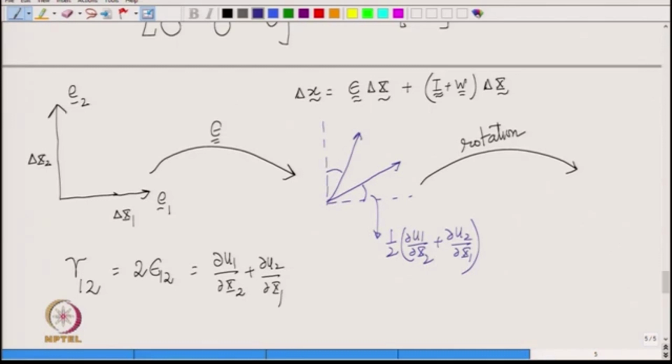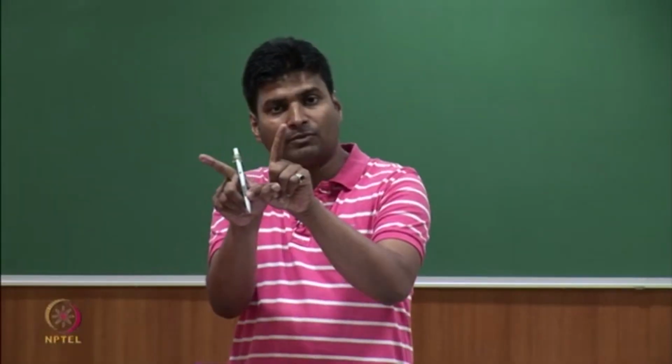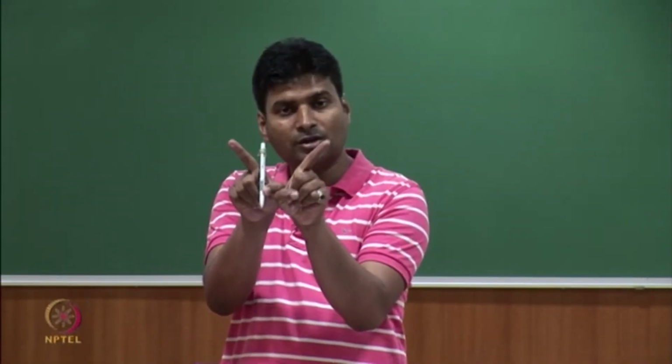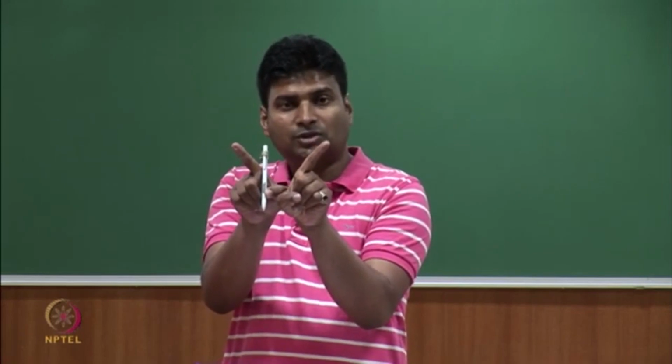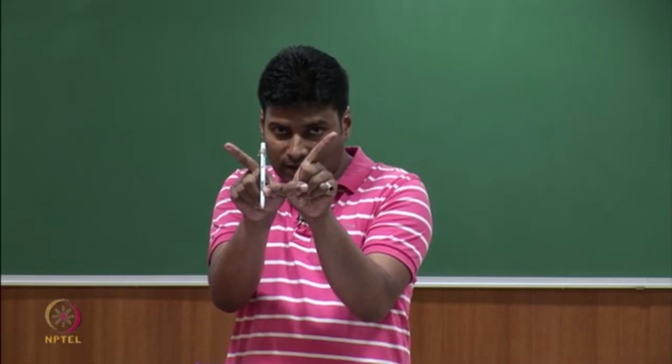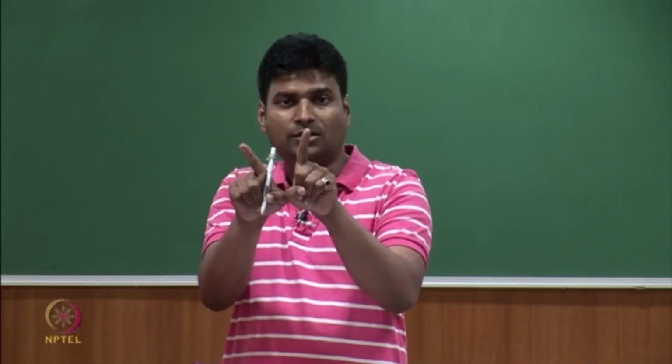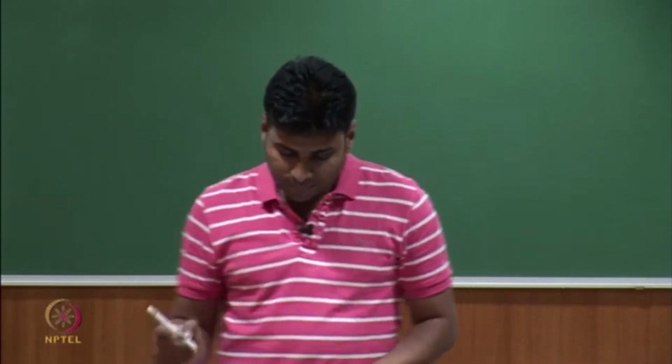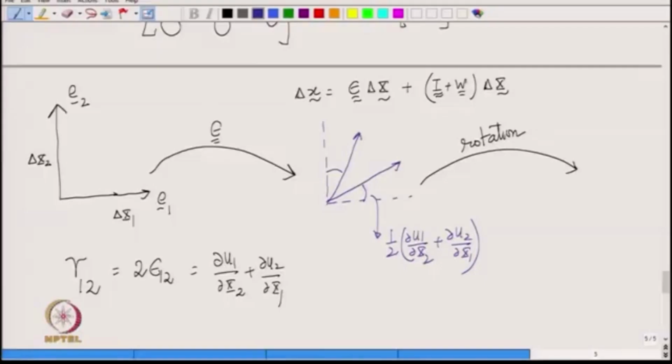You see the bottom line, the E1 line rotates anti-clockwise about the E3 axis, whereas the E2 line rotates clockwise about the E3 axis. If you rotate both of them in the anti-clockwise direction, then you do not get any shear, right. If both of them rotate in the same direction, then the angle between them does not change, and that corresponds to rigid rotation. Shear means both of them have to rotate in two different directions, then only the angle can change, right. Okay. So, this is just a shear part and then the rotation part, correct.